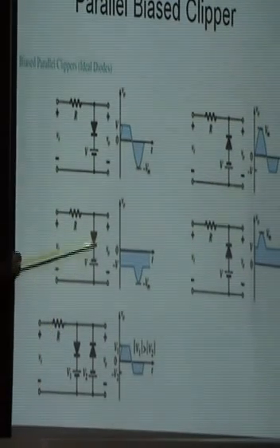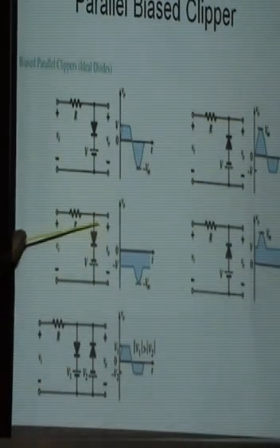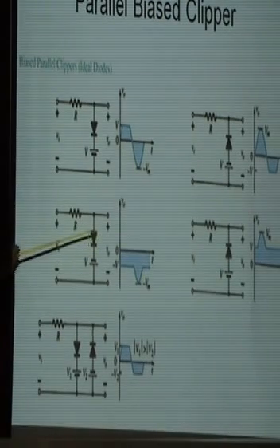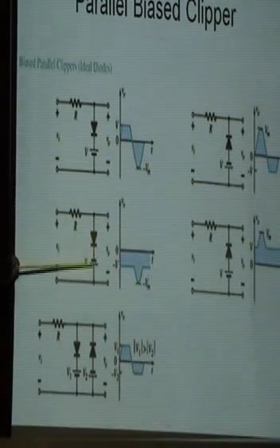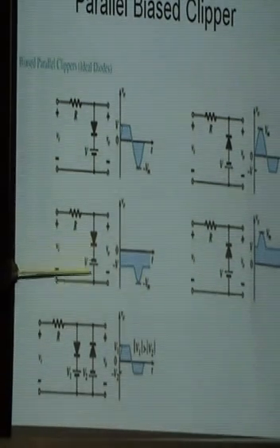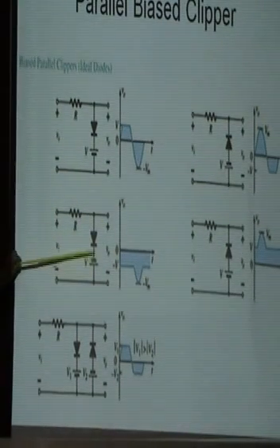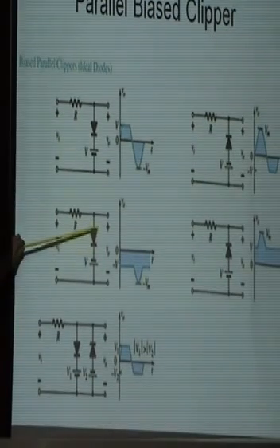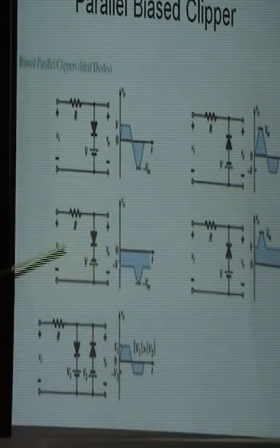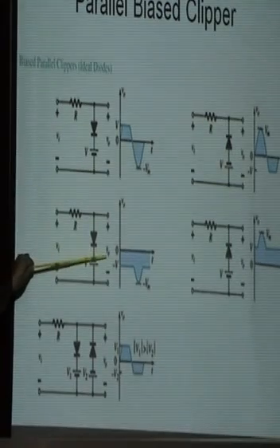While here there is no question, because if the circuit is opened by this switch, then either V is shown or V is not shown. There must be no concept of adding voltage. So it is only that for the reverse half cycle the diode is an open switch and the path is not here. So Vi directly appears across V0.